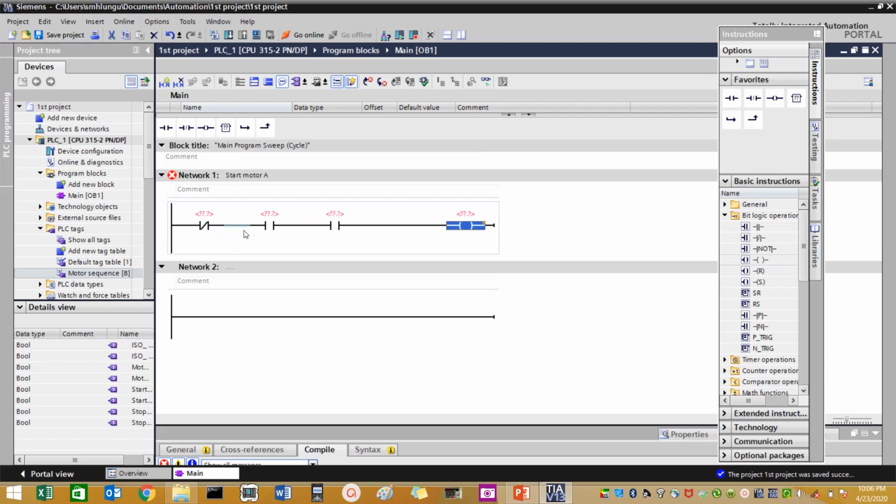But as it is for this arrangement, because these are push buttons, if I were to press this button here, this motor will start running, but it won't latch, it won't retain itself. So I need to create or design a retaining branch, which is going to be across here. Are you with me?